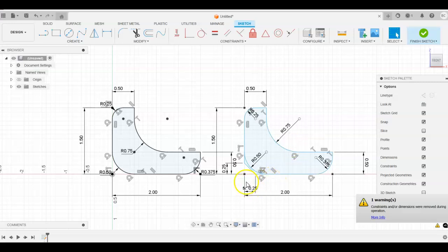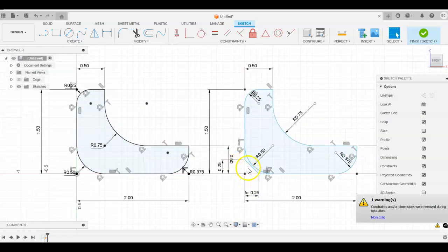So now notice the equal distance chamfer is going to create 45-degree angles, or 135 degrees on the inside here, and the distance when we specify this is from this point to that point, and from here to there as well. So this is an important thing to remember, especially on engineering prints, where those dimensions come from.